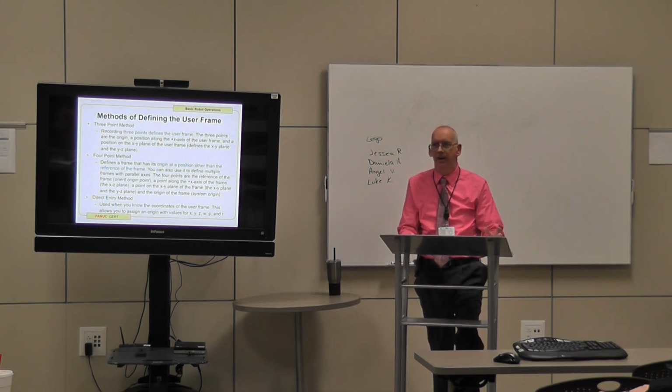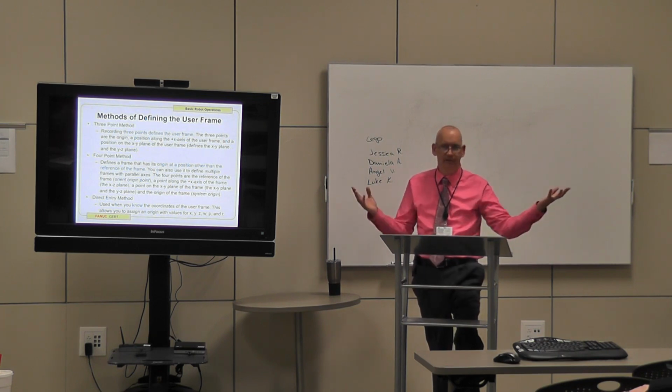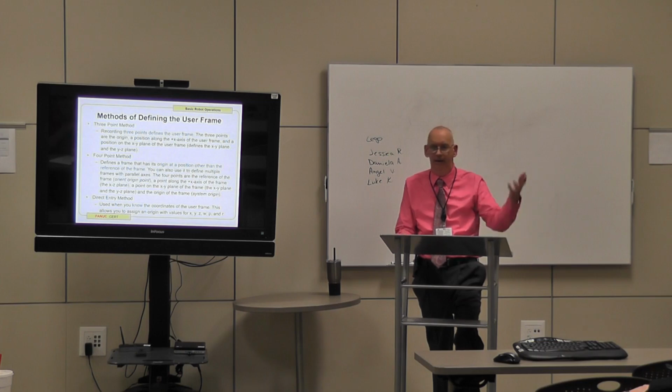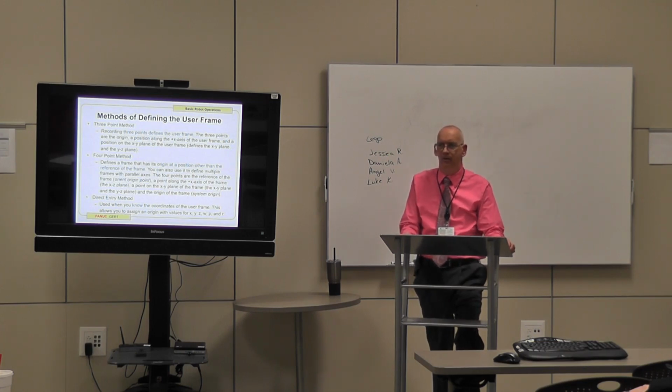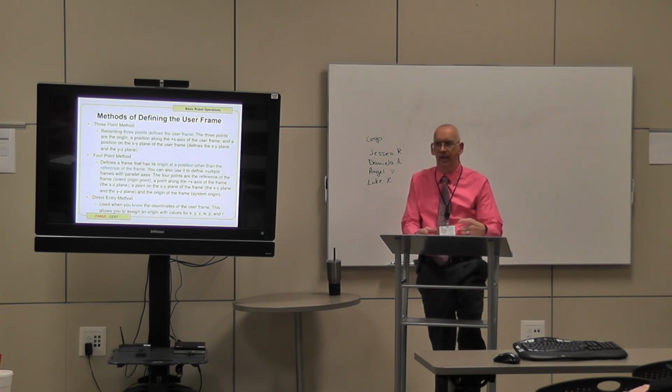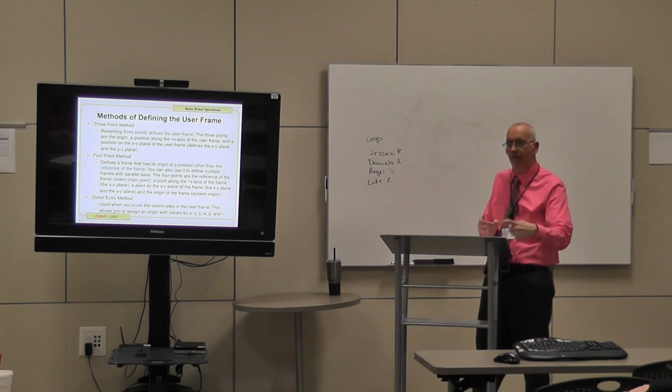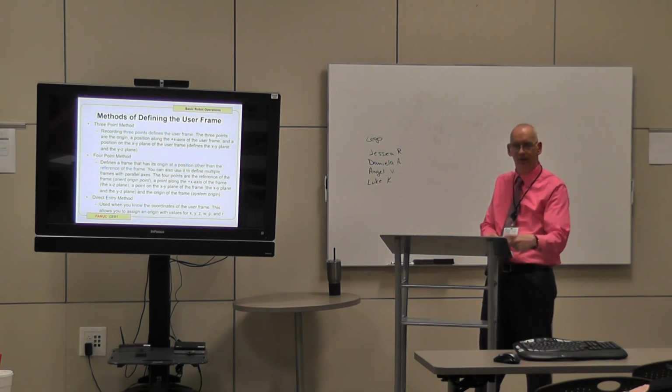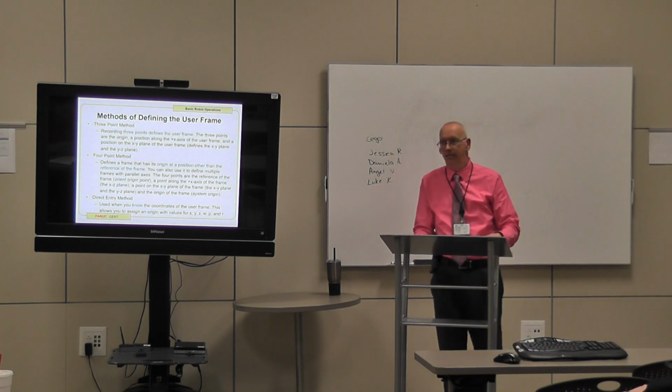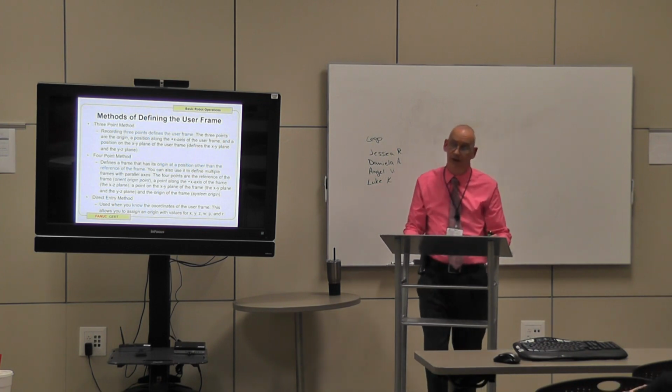Because now it's a matter of aligning your frame correctly, because I have 15 of you people and then I have 10 more. Okay, and each one of you is going to be assigned your own frame where your box is going to be located. So if you decide that your box is going to be a little bit on this side over here, you need to make sure that each time you go to do a program, that's where your box is going to end up being. Because that's where you're going to assign your user frame.